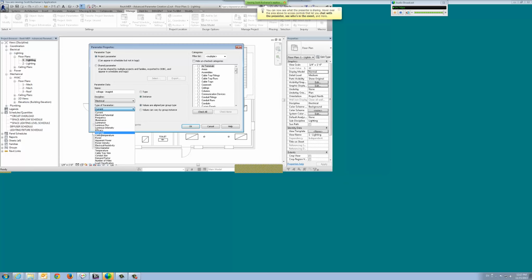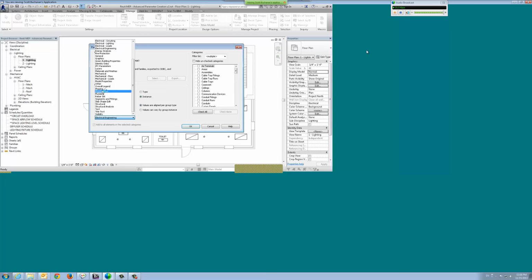Now, if you're unsure what these different types of parameters equate to, you can go to your project units, take a look at those, and it'll actually define them. You'll see that electrical potential has a V for voltage next to it. Current has an A for amps, and so on. If you're getting familiar with how they've named this information, you can get that breakdown there. So we're going for voltage, so it's electrical potential. And as far as grouping it under, again, no bearing on functionality. You can put this wherever you want, just so we can easily see it. I'm going to throw it in the under section there.